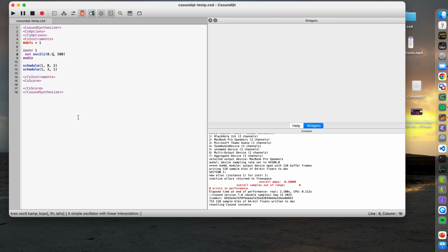And after that, you can invent your own. So for instance, I can say that P4 is going to give me my amplitude, and P5 is going to be my frequency. So I can go P4, so let's say 0.1, and P5, 500. For the next tone, I'm going to last for 1 second, and I'm going to play it a little bit louder, and at a lower frequency, 100 hertz. So when I play this,